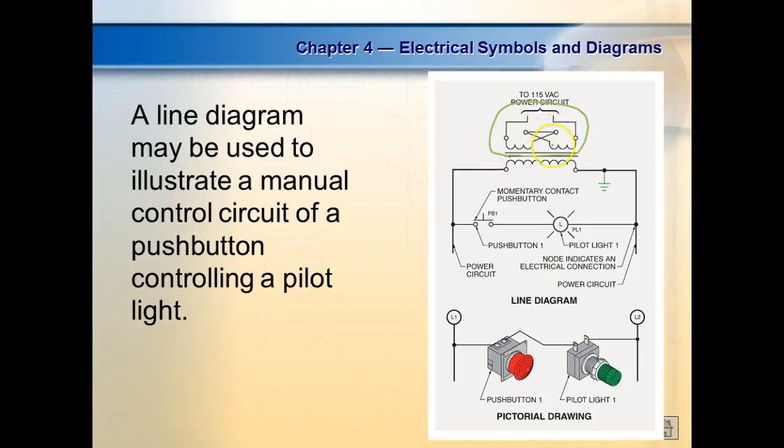So notice up here on the primary side, we've got these jumpers up here that we jump depending on what we want to do. Our ultimate goal is to get 120 volts right there, because all our relays are rated at 120 volts. All our light bulbs are rated at 120 volts. So everything we hook over on this side is going to be rated at what? 120 volts. If I put 240 volts on them, what's going to happen? Well, they're going to all burn up, because if we double the voltage, power goes up by 4, right? If we put 60 volts on it, then they will do 1/4 of the work.